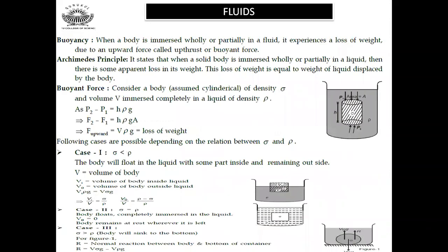Now buoyancy. When a body is immersed partially or completely in a fluid, it experiences a loss of weight due to upward thrust. We call this force upthrust or buoyant force. Now Archimedes' principle states that when a solid body is immersed wholly or partially in a liquid, there is an apparent loss in its weight, and this loss of weight is equal to the weight of the liquid displaced by the body.